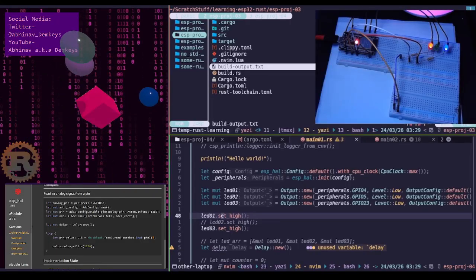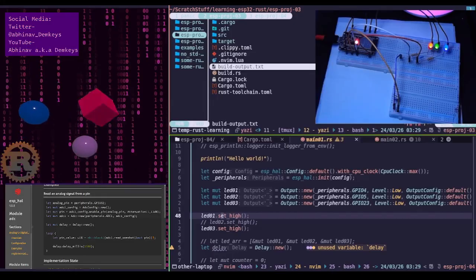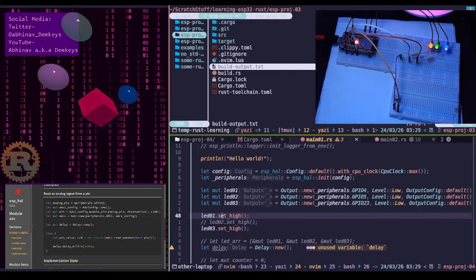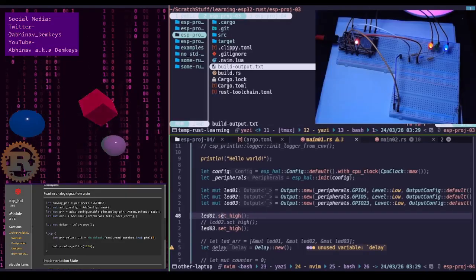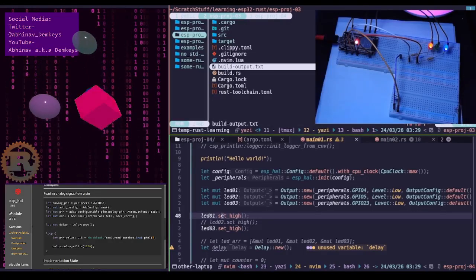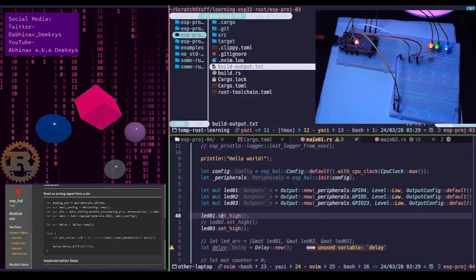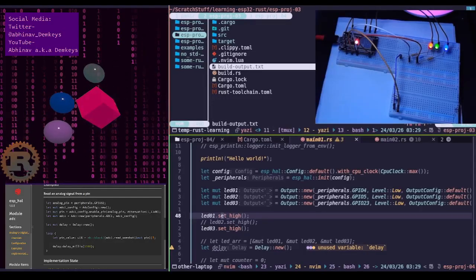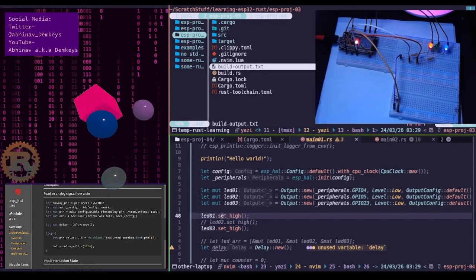So I was trying to apply a bit of solder onto the wire first, because generally what they recommend is you apply a bit of solder to the wire itself. That's called tinning the wire, and then you also tin, let's say you're soldering something to the potentiometer leg, that leg as well.